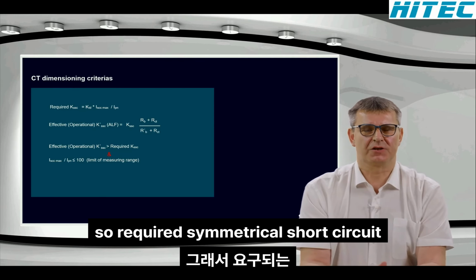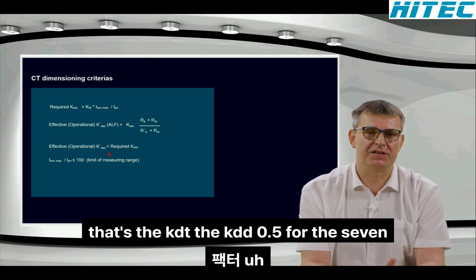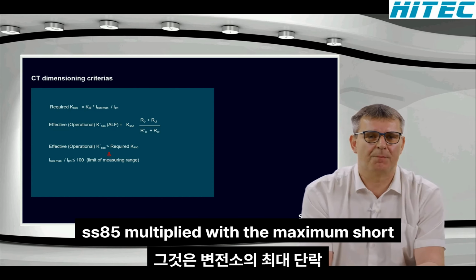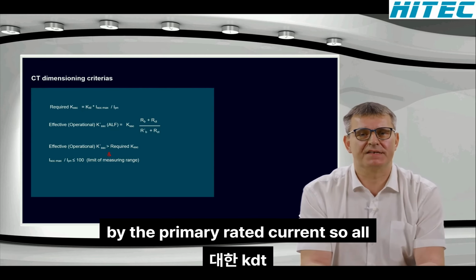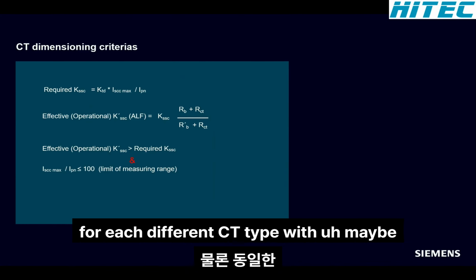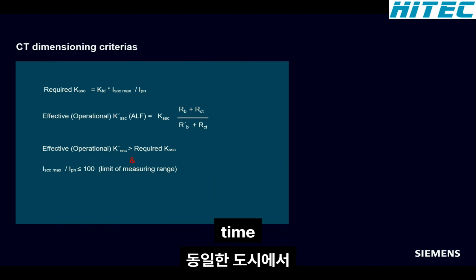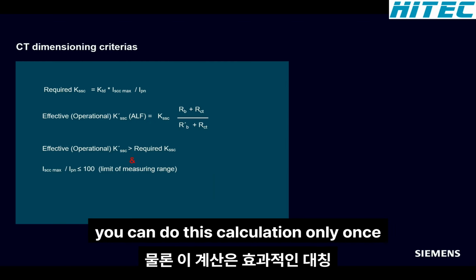The required symmetrical short circuit factor, that's the KTT, 0.5 for the 7SS85, multiplied with the maximum short circuit current of the substation divided by the primary rated current. All these considerations must be done for each CT, for each different CT type with maybe different ratios. If the same CT with the same CT ratio is used every time, of course, you can do this